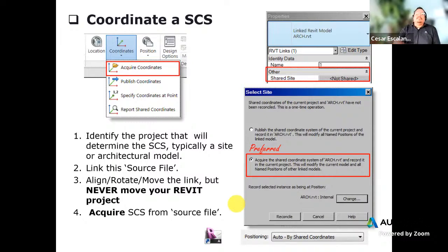In AutoCAD, you say just select everything and move it 6 inches. In Revit, you cannot do that. Once you build a model of a certain size, it becomes really, really difficult to shift your model. And even if you could do that, the camera views of every single floor plan and detail plan are going to get displaced, and then you have to go back and fix every single view.